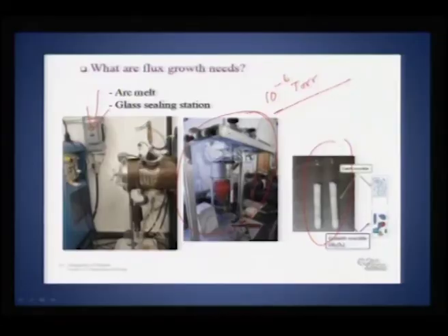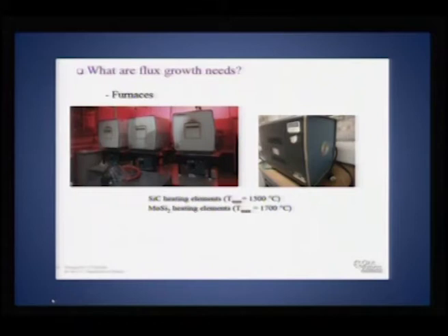What you see here are the alumina crucibles, which are called growth crucibles, and then you have catch crucibles, which are usually quartz. So, quartz is actually used for sealing the crucible, and inside the quartz you can have alumina crucibles with your material. So, this is the way you do it, and typically you need a furnace to grow these flux grown crystals.